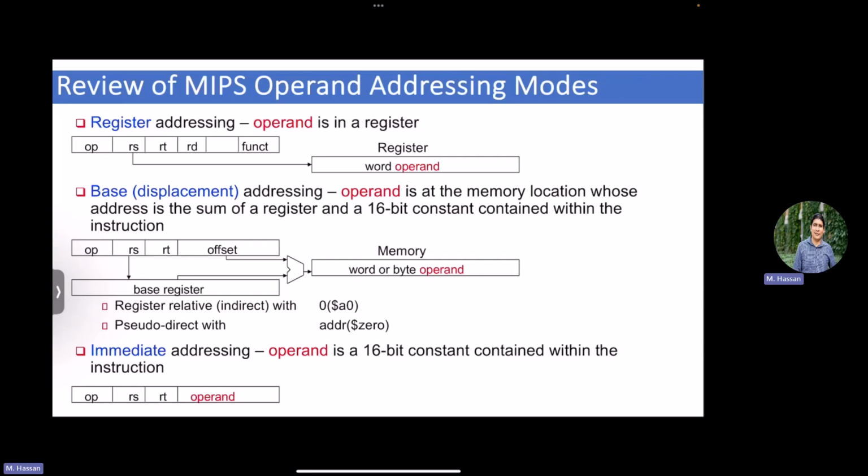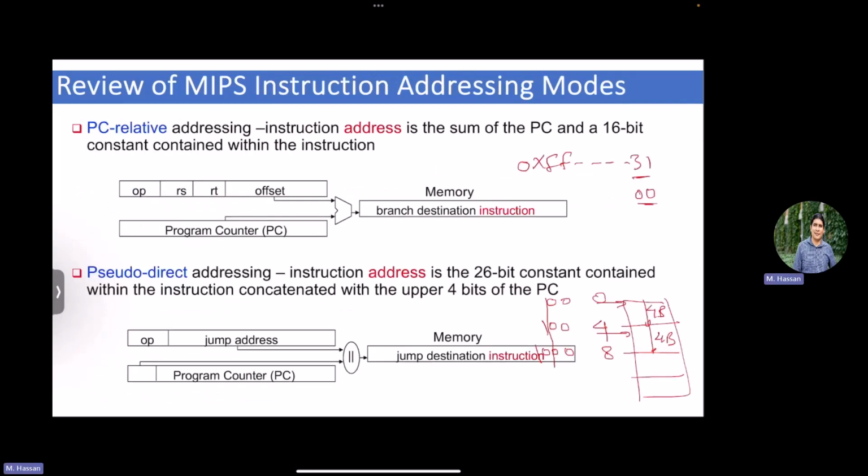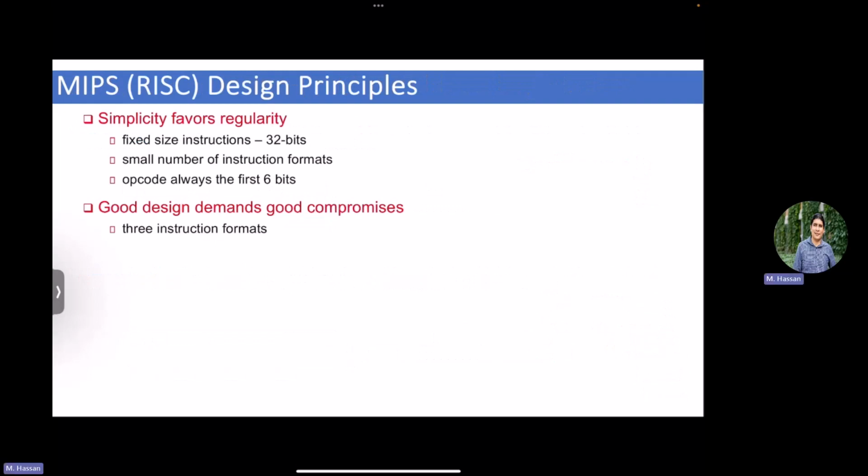If I'm writing a decode unit hardware and I need to extract the bits to understand what instruction it is, you always know that you can basically wire the most significant 6 bits, for example, to be able to decode what the instruction is. And based on this, you know where to find the remaining fields, right? So this is like a header. You start with it to be able to understand what happens in the remaining fields. If it was in different places, well, it becomes way more complicated. But CISC also defined a fixed place for them. Otherwise, it would be very hard to figure it out.